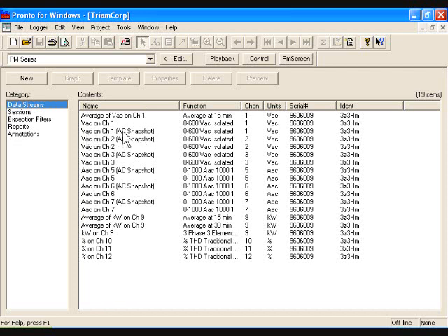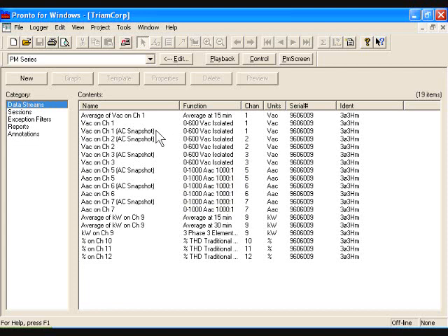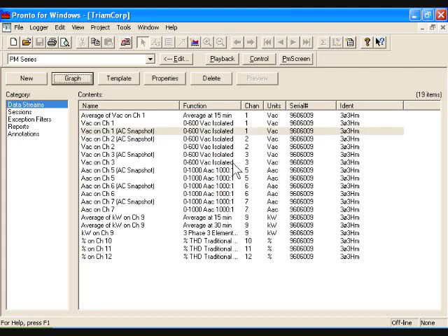This data was taken with an older Ranger called an HA5000 that did waveform capture. And so we're going to show you how to look at the waveform capture data so that this video may be used once the 7000 is released, because we want you to look at this feature. It's a very powerful feature, as you'll see. We're going to look at the AC snapshot, or transient it will be called, I believe, on the PM7000, of the voltage here. So we're going to select the voltage channel, and we're going to look at some waveform captures now.